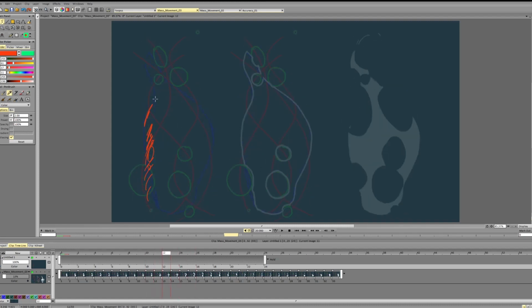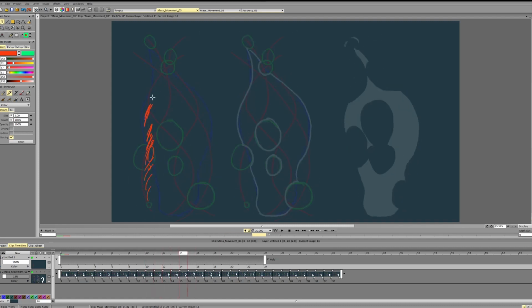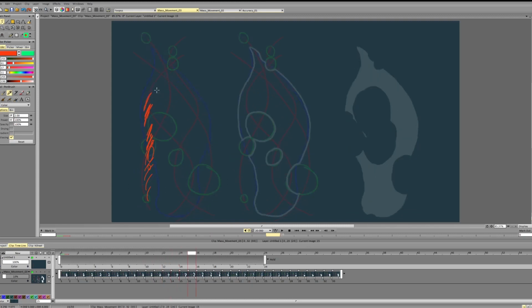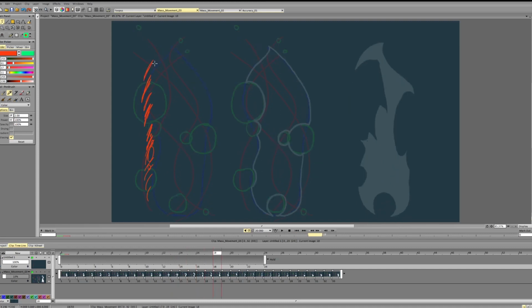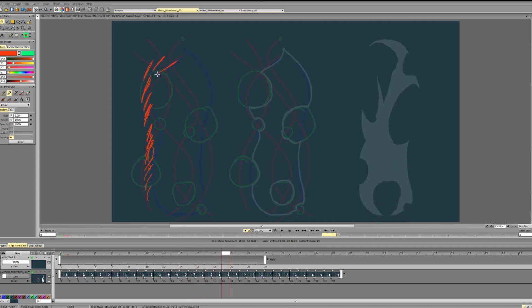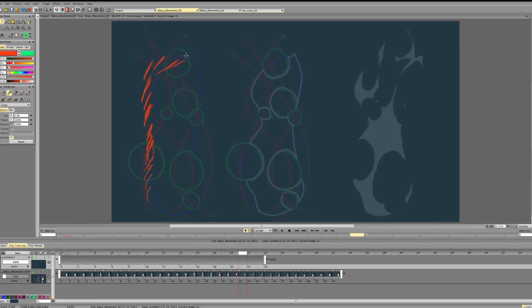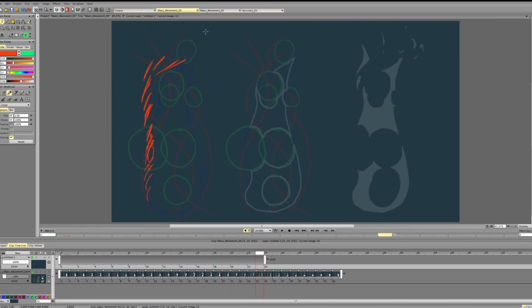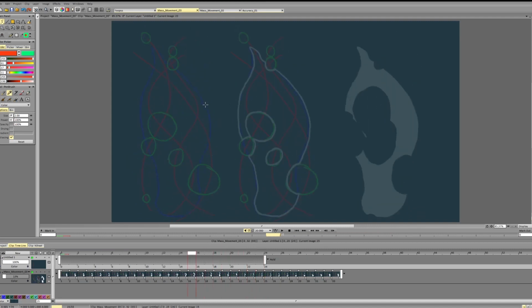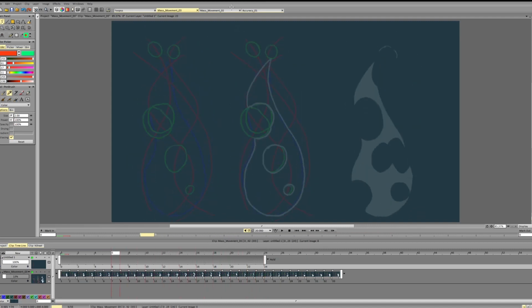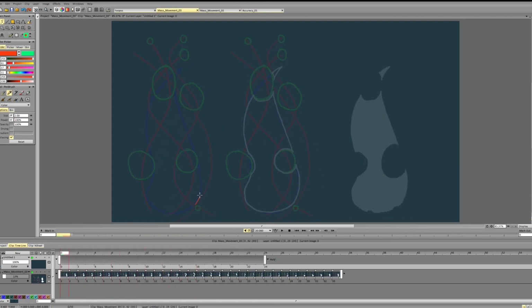Then again, we're decelerating suddenly and then accelerating. Going like this, suddenly decelerating, accelerating. And then you see we suddenly change the position. And it happens quite fast. So we would need to change this up a bit and get more gradual base motion for that to work a bit better.